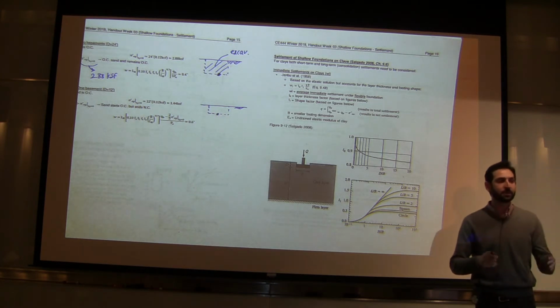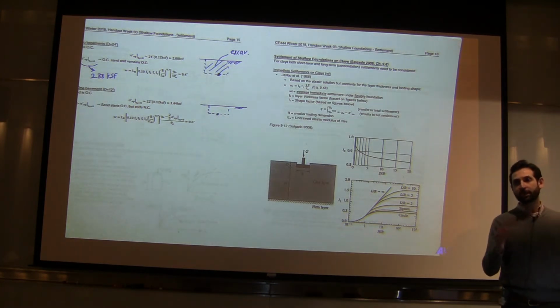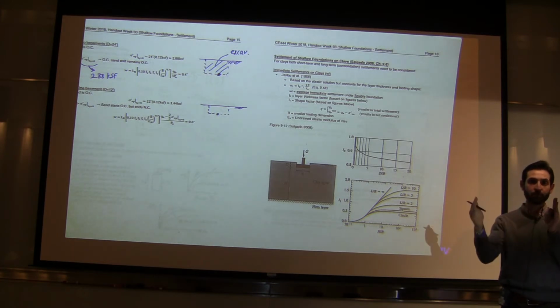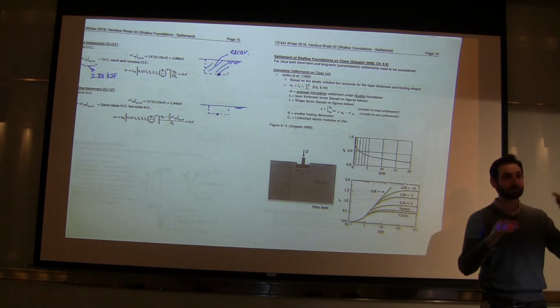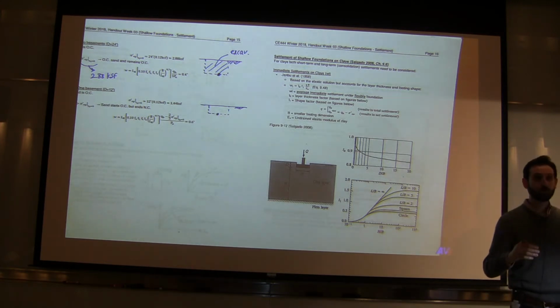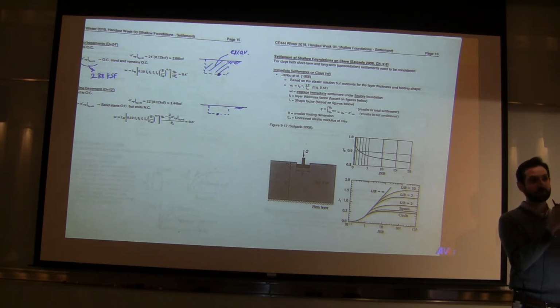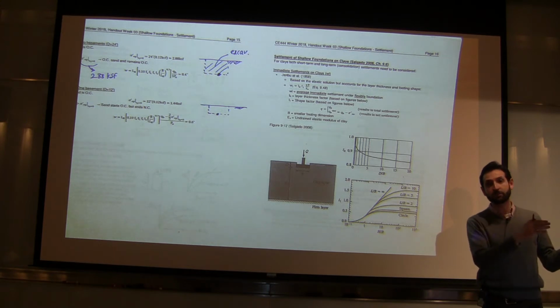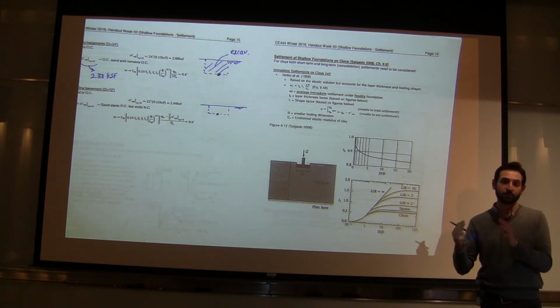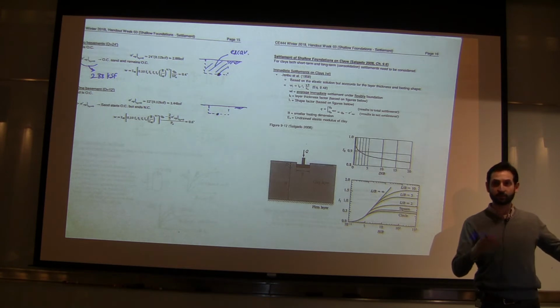For sand, we didn't really get into the difference between flexible and rigid, and whether it's the average or at the center or the edge. And I don't want you to get bogged down with that, because that equation was based on empirical equations, based on those 200 stories, all designed for factor of safety of 3, and so on. So what they gave as the settlement was just an average settlement. And some of those cases may have been flexible foundations, some of them may have been rigid foundations. We don't want to get into the details of those.